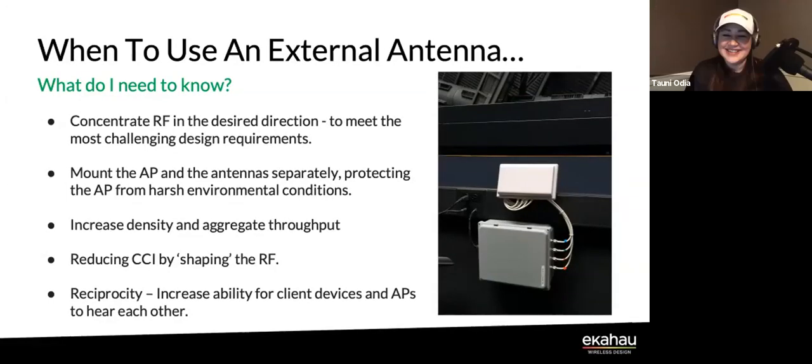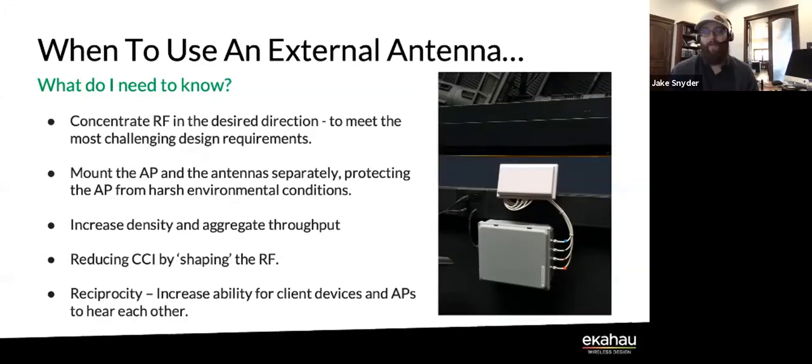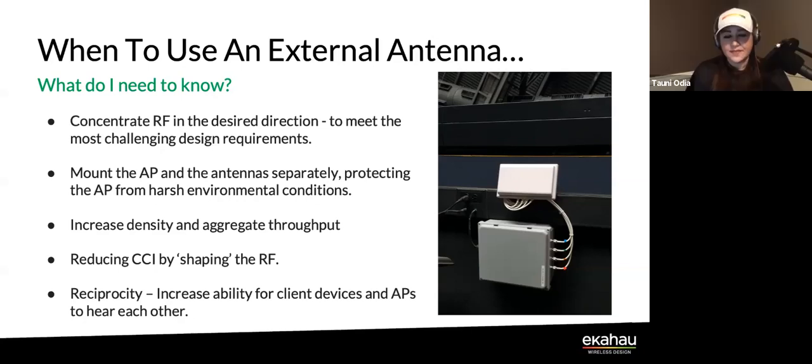Awesome. Absolutely. The other piece I would say on Sam's point: because antennas are reciprocal, we can exclude them from a lot of the things we're talking about, but you still have to keep in mind that if you're operating your access point at higher power than the client is capable of, there can be an issue. I'm not saying they have to be balanced, but you can definitely get to a place where an AP can transmit to a distance where a client can hear it, but not necessarily the reciprocal. So we still have to stay within reason in terms of transmit power with directional antennas. Yeah, absolutely.